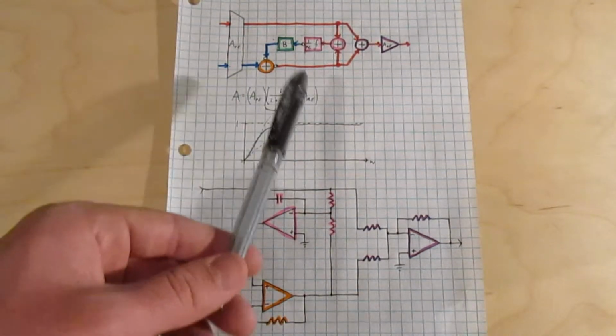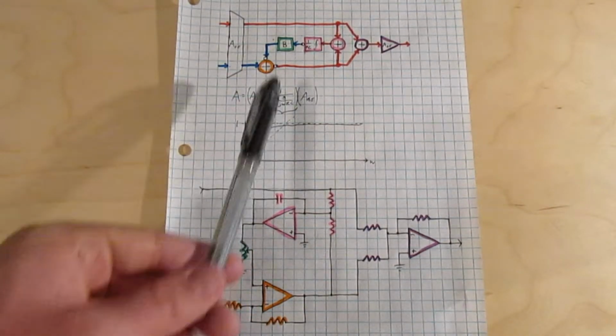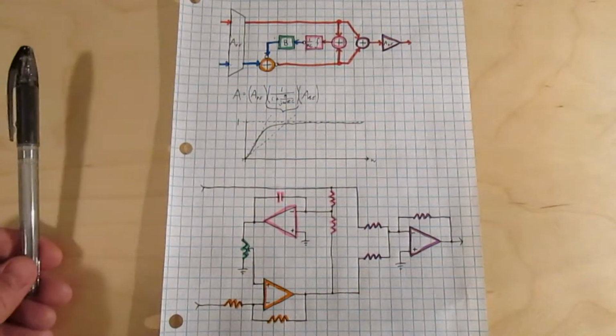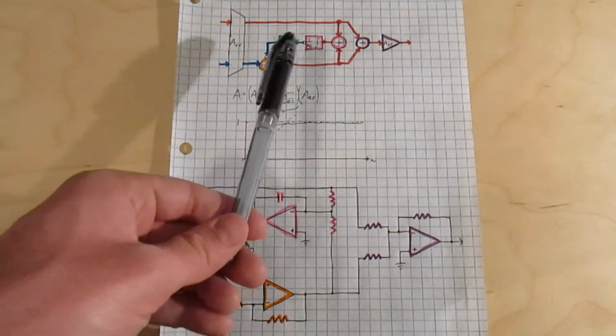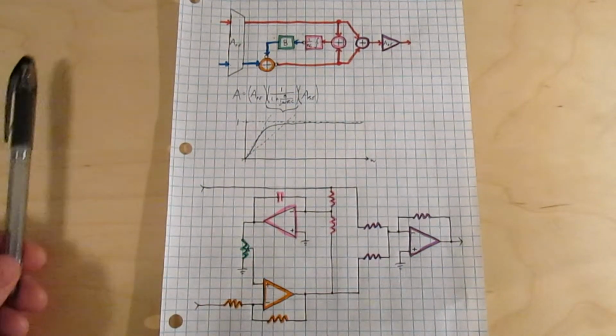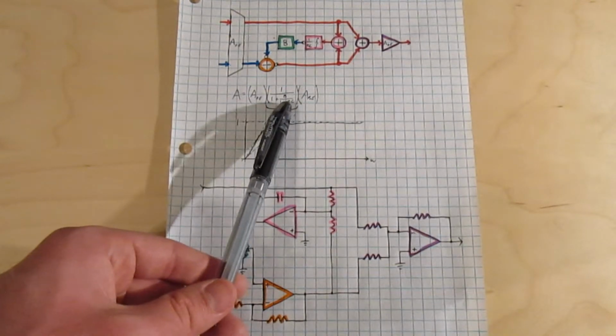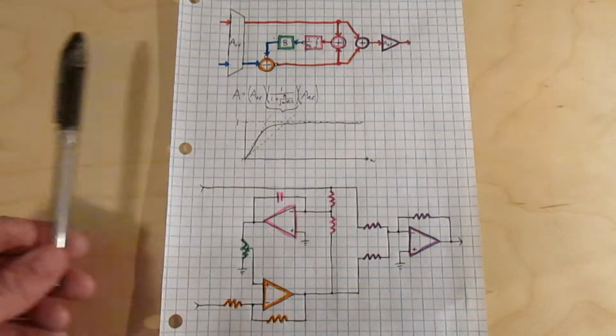In case you don't know, an attenuator is basically the opposite of an amplifier. Signals that go in come out smaller. So now the gain of the feedback path is B over j omega RC, where B is the gain of the attenuator. And since the gain of the attenuator is going to be less than 1, that sort of has the same effect as making either the resistor or the capacitor larger.